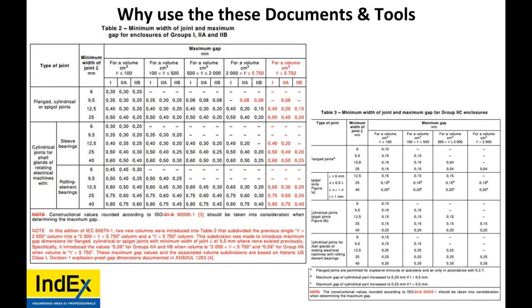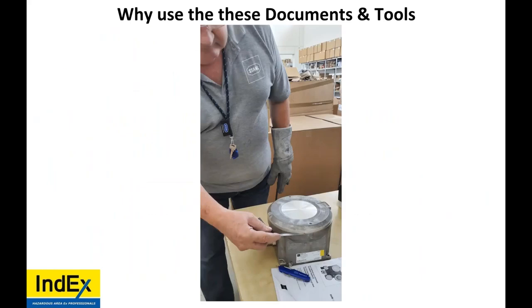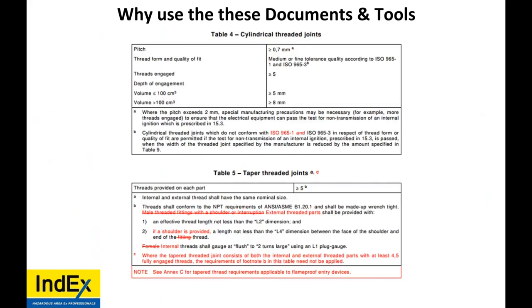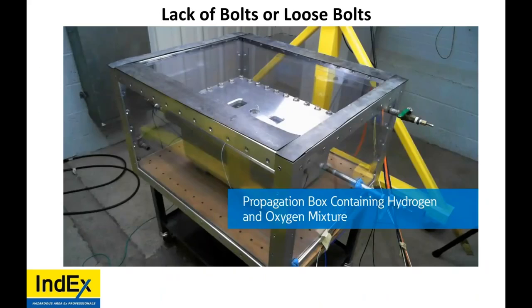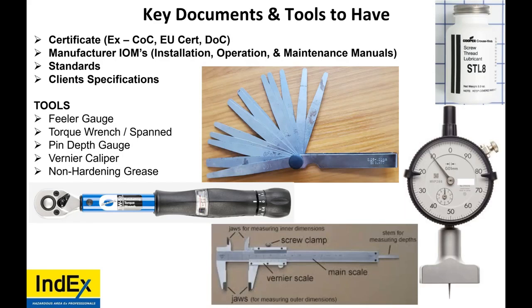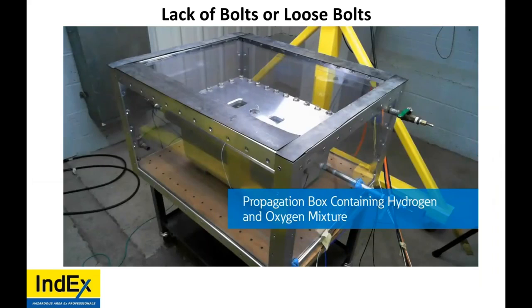Shouldn't the grease used on the flame path be a non-petroleum based lubricant that does not propagate out the flame path of the enclosure? Correct. So this is just my favorite type, okay? I'm not telling anybody that. Cooper Crouse-Hinds STL standard thread lubricant, it's lithium based. So it's got a high dielectric strength, actually gives you continuity between your cover and your enclosure, non-hardening, increases your rain tightness, doesn't increase your IP rating, it assists it. I put it on the bolts, the cover, and the threads of the gland.